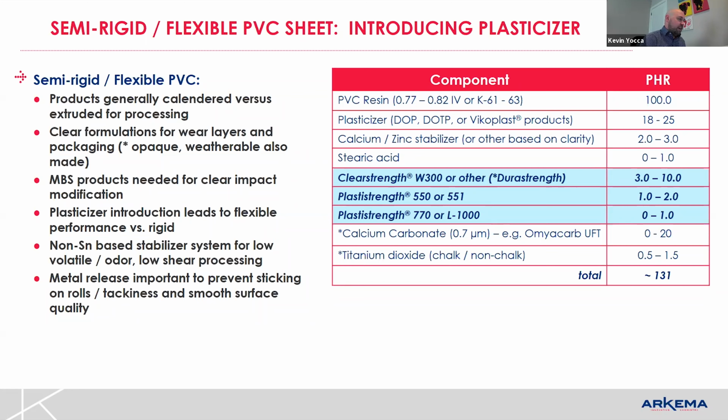I don't know what kind of an artifact it'll give you, but if you think of incorporating the regrind and making a homogeneous polymer at the end, honestly, if you do DSC on the full PVC article, including the regrind and whatever else is in there, if you've done a good job processing and you have a homogeneous melt at the end where there aren't, under microscopy, clear macro regions or microstructure of the regrind pellets themselves that aren't broken down, my guess is you should still get some indication of the process temperature and the level of secondary crystallites that are formed to give you an idea what gelation is in the full compound.